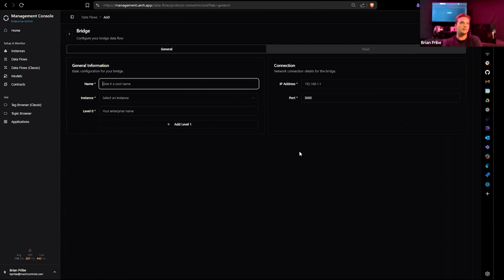And in this one, this is a program for a tube bender conveyor, where it's got like some conveyors, there's a robot involved with it, there's some vision, but everything is just with IO. And all of the names in it, it's just terrible. It's garbage PLC code and logic, but it still produces millions of dollars in value for the customer day in and day out. So having that machine go down or somebody trying to make changes to it just really doesn't make sense for the manufacturer. And this is where having UMH at the edge to be able to collect the data from these disparate type of devices, unifying them and getting them in is really going to provide a lot of value for you.